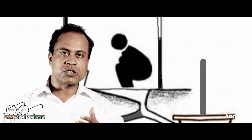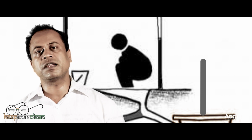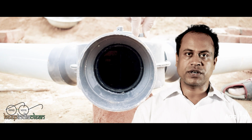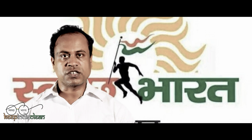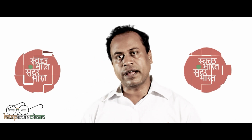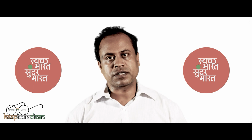Sometimes we fix a vent pipe which not only spreads smell but also obstructs the process of fertilizer formation. Absence of an inspection chamber or Y joint also creates problems. So, if we give due care to these little and important aspects of construction, then there will not be any problem in constructing the toilet and in use of the toilet.